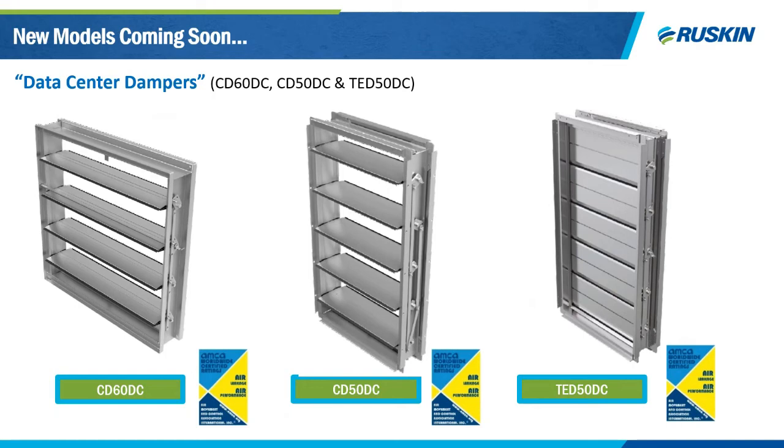So all 3 models are energy efficient and AMCA certified to meet a class 1A leakage rating of no more than 3 cubic feet per minute per square foot at a 1-inch water gauge. And what you see here, we have the CD60 DC, the CD50 DC, and the TED50 DC. The CD60 is built of galvanized steel. It is our most economical choice. Next up is the CD50. That's built from extruded aluminum, so the blades and framing are extruded aluminum, and it's great for corrosive environments.